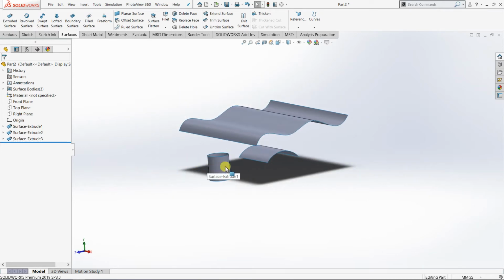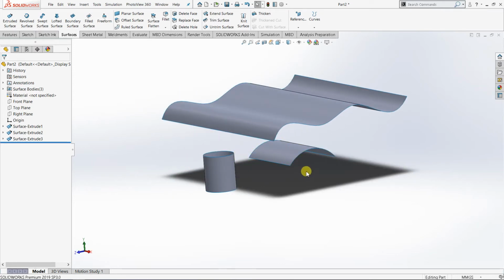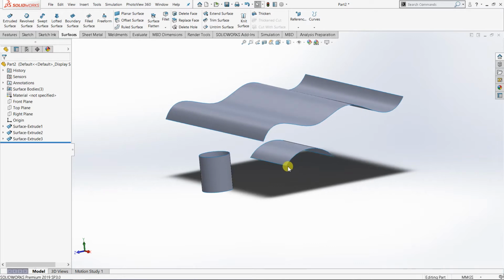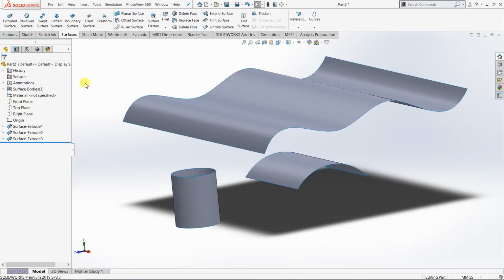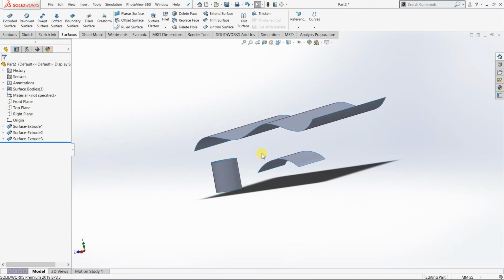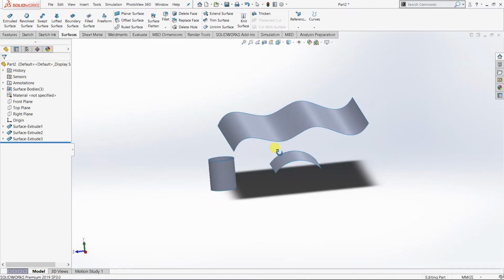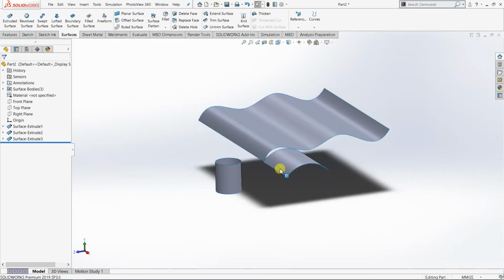So you have to remember that the main difference in SolidWorks for both 3D solid modeling as well as the 3D surface is that the sketch for the 3D solid modeling should be in closed loop, whereas for the 3D surface, the sketch is not necessary to have a closed loop. It also can be an open loop. All right. So as what I've shown to you over here.